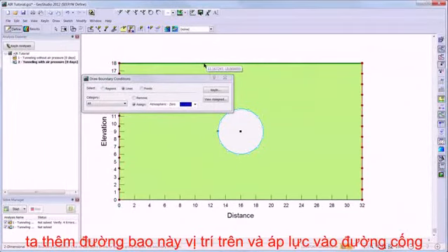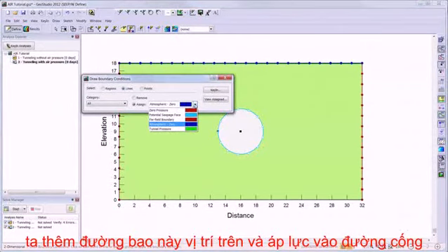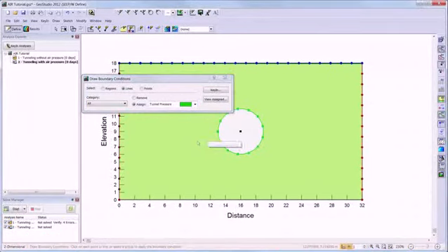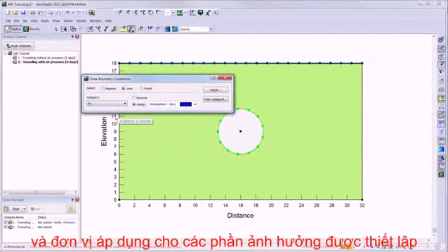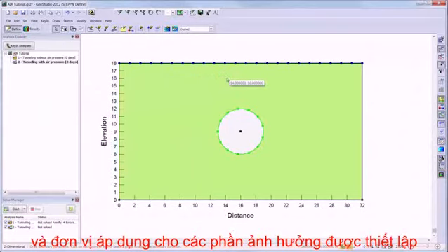We will add the zero atmospheric pressure boundary condition to the surface of the soil domain and the tunnel pressure to the line representing the outer rim of the tunnel. If at any time you wish to only see the airflow boundary conditions on the domain and remove the hydraulic boundary conditions from the visualization, you can change the drop-down menu from All to Air. Note, the hydraulic boundary conditions are still applied to the domain, but are simply not a part of the visualization.